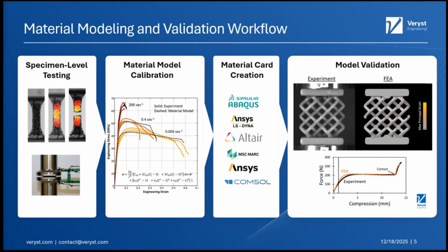That's a great question. If your material is manufactured the same way, a larger versus a smaller sample should not give you a different material behavior. You should be able to have a very large dog bone versus a very small dog bone and get the same thing. So sample size doesn't inherently affect those properties.